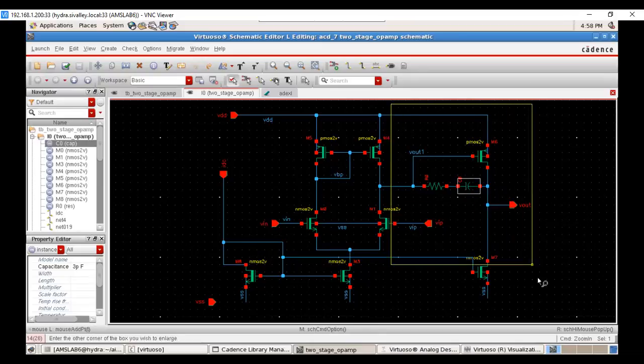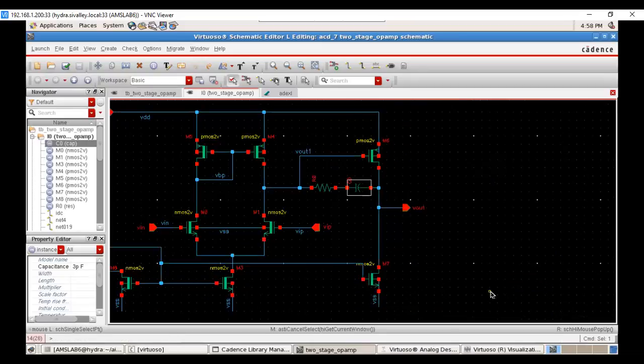To avoid that, we are familiar from the stability discussion with how to cancel the zero effect and the pole effect. It is just the opposite. If a zero is creating a problem, place a pole on top of the zero, meaning the pole frequency and zero frequency should be the same. Similarly, if a pole is causing a problem, keep a zero on top of the pole so that the pole effect is cancelled out. That's what we are trying to do here.